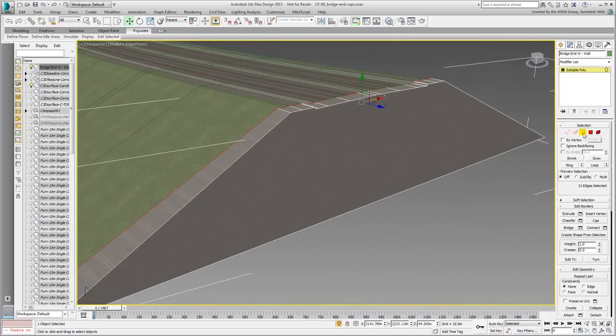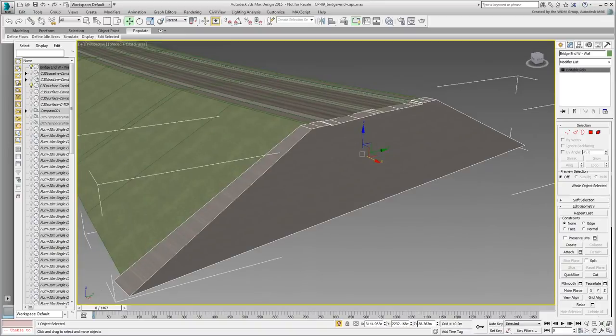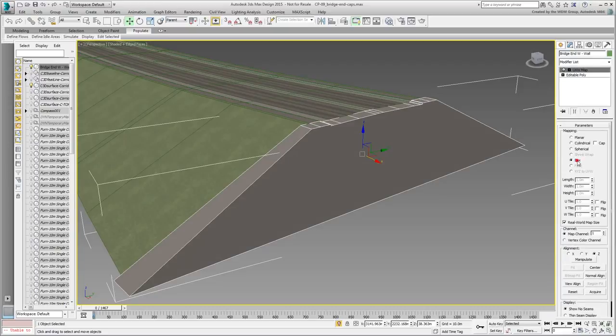The geometry is pretty much in place, but you need to adjust the mapping. There are currently pixel streaks everywhere. Apply a UVW Map modifier in Box mode and disable real-world map size. Adjust the gizmo size to values that work better. Try 40 by 40 by 40.